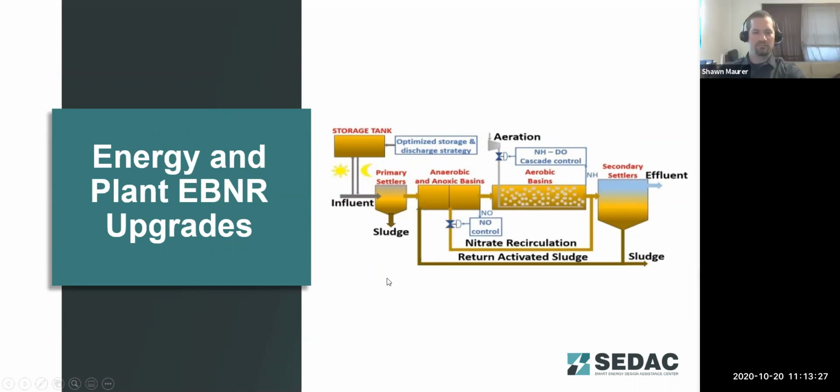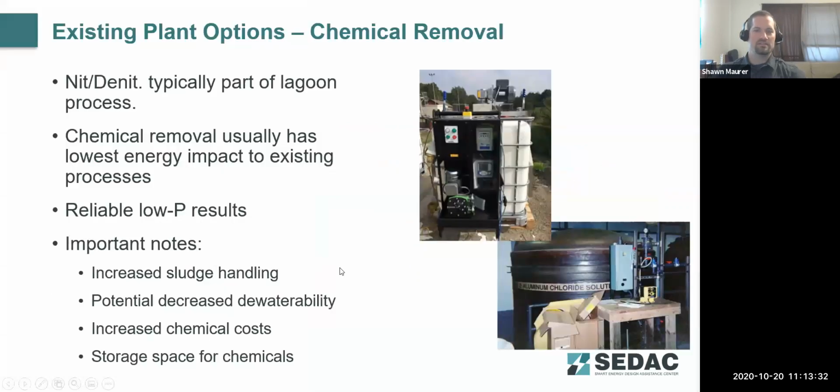Thank you very much, Ryan. I wanted to just go through briefly some of the different phosphorus and nitrogen removal strategies and their energy impacts for plants. One of the most common ways for phosphorus removal, as Ryan noted, is chemical removal. You're looking to precipitate phosphorus out by adding a chemical salt that the phosphorus will bind to. It becomes heavier, and then it can settle out in either a filtration system, or in a secondary clarifier or tertiary clarifier.